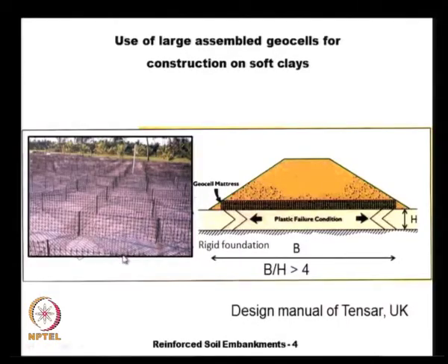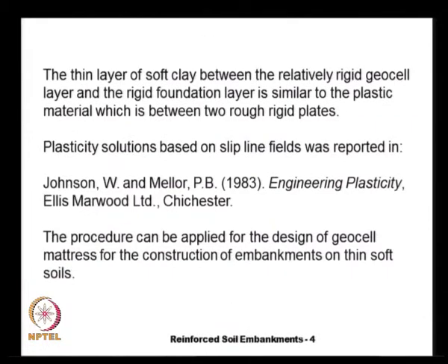And here on the left hand side we see the Geocell mattress being fabricated, and this particular photograph is from the design manual of Tensar company, UK. The thin layer of soft clay between the relatively rigid Geocell layer and the rigid foundation layer is similar to the plastic material which is between two rough rigid platens, and for this case the plasticity solution was proposed by